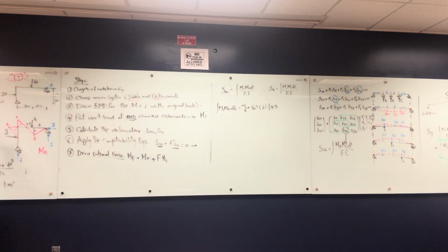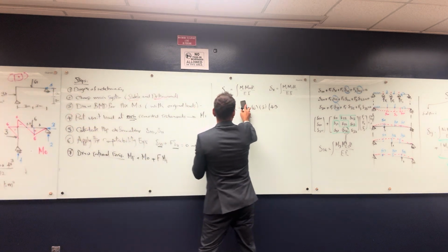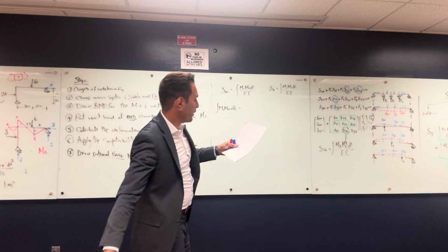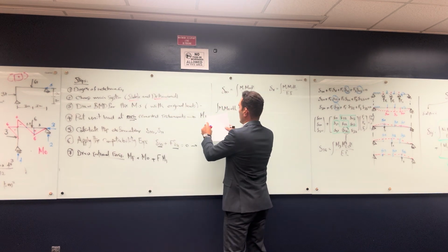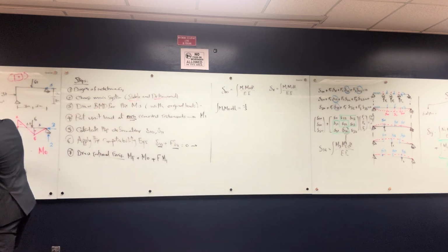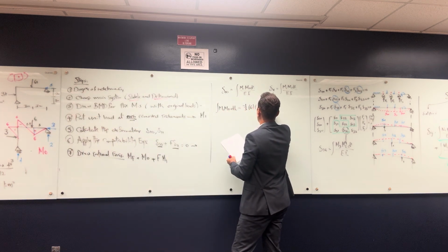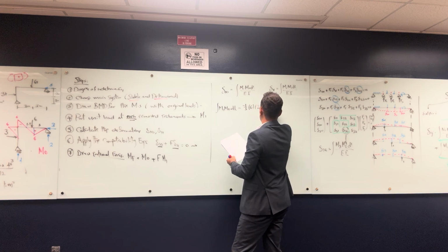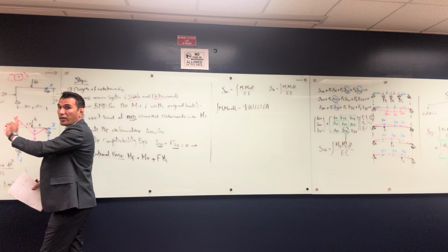Let's pick this triangle with this triangle, a small one, and then this trapezoid with this triangle. So both of them are negative, so I'm gonna put negative. You guys look at the table and tell me, triangle with triangle is gonna be negative 1/3. M1, M3. M1, M3, that's very easy. I have M1 is 6, M3 is 2, 6, 2, and multiplied by the length, which is 3. This length. All right? I'm done with the first triangle.